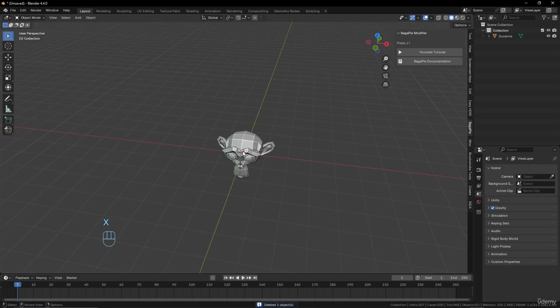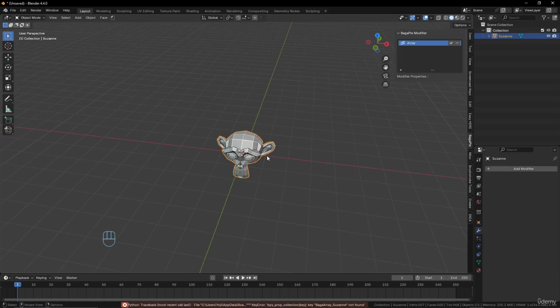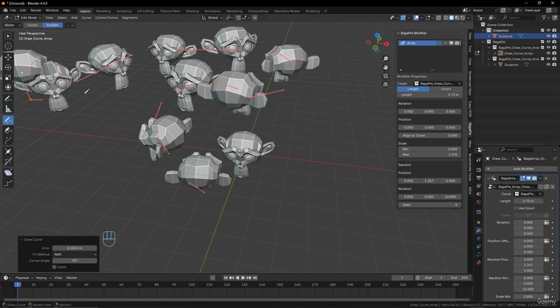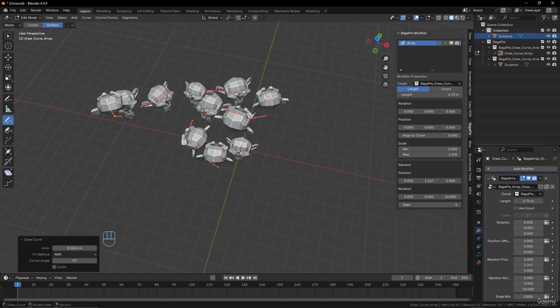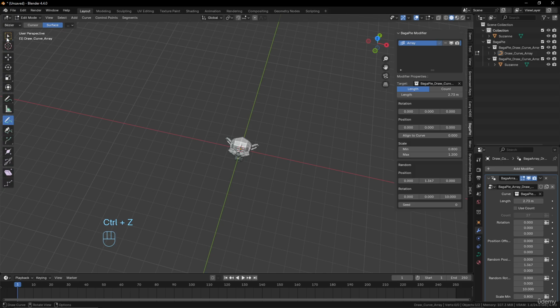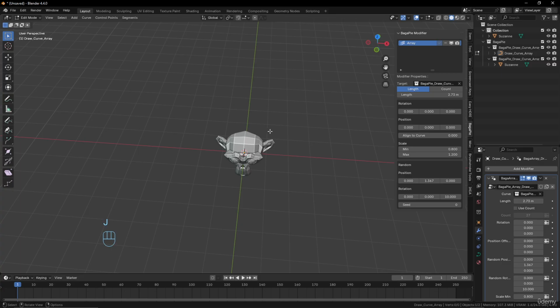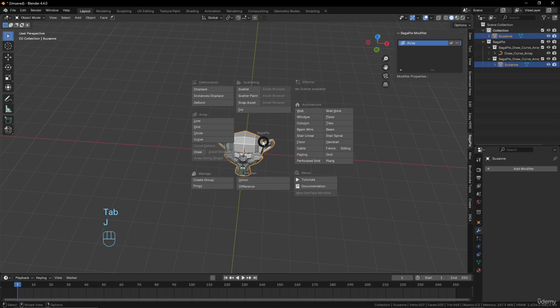And what we can see as well, so that's it for basically, there's options here. You have the curve deform as well. You have the draw array. So for example, if you draw just like this, you will have an array into a curve that you just created. So again, it's just a gain of time. It's just something that you can do basically with Blender, but it's just more simple to put J like this and use it that way. So it's really more effective. Okay.